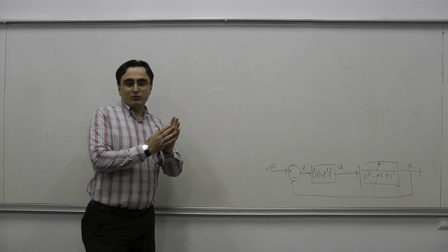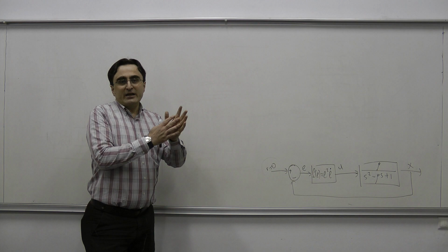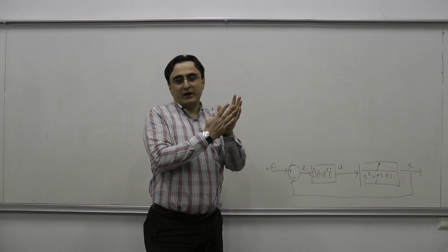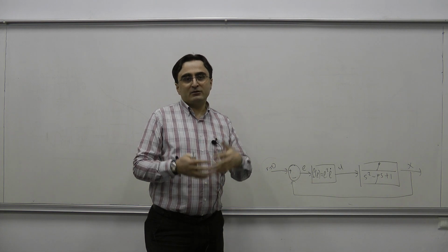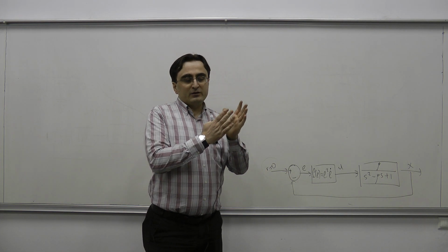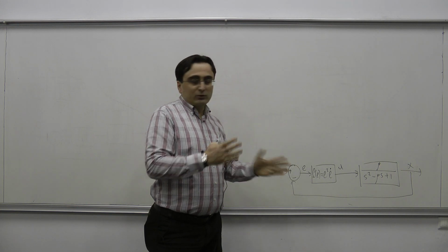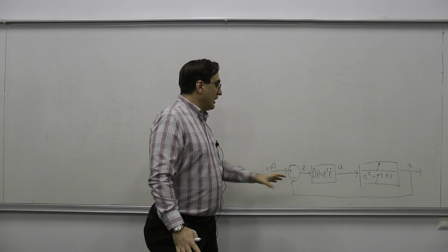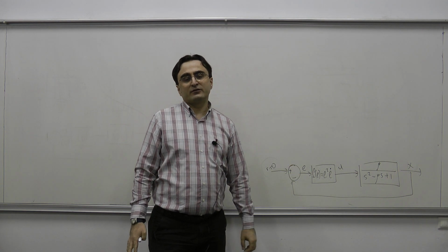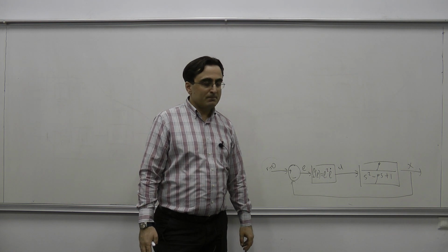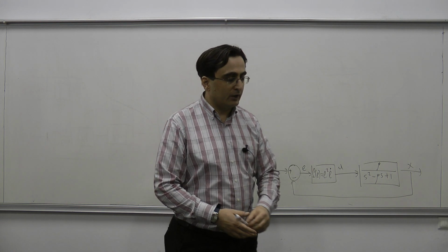But in frequency domain, I know that an oscillation would really cover a very small frequency range. If I have an oscillation with some frequency, then in frequency domain, the frequency coverage of an oscillation might be really small. That is why describing function analysis makes the linearization in frequency domain. Okay? That is what we are going to do here.